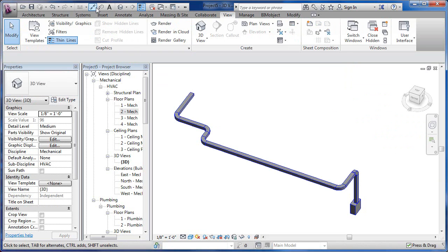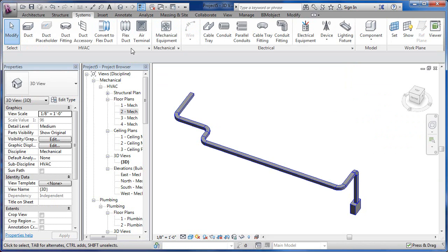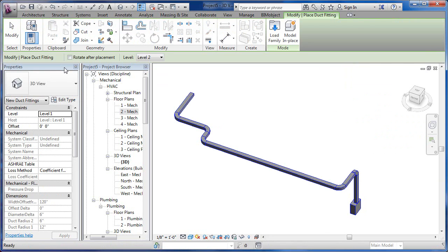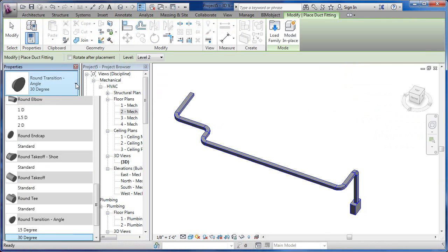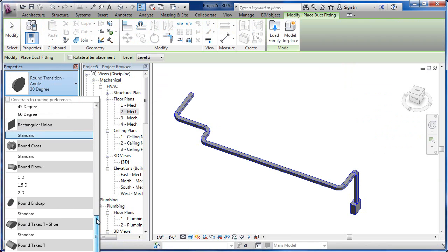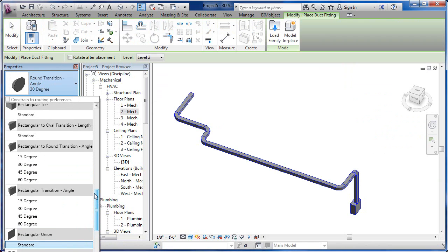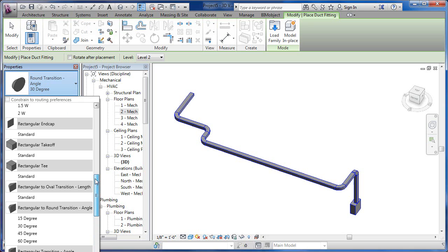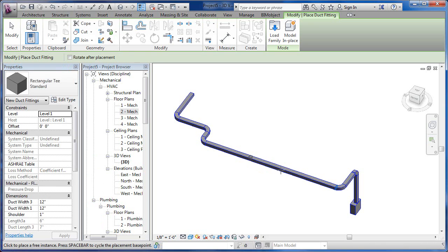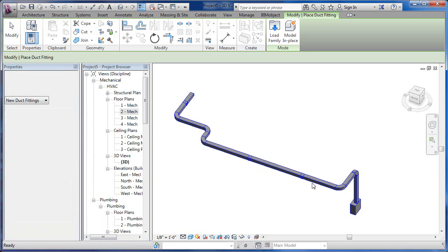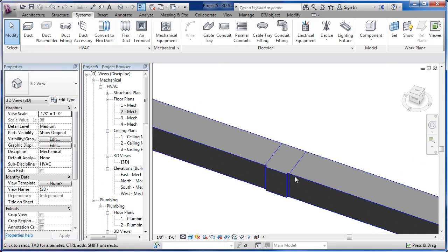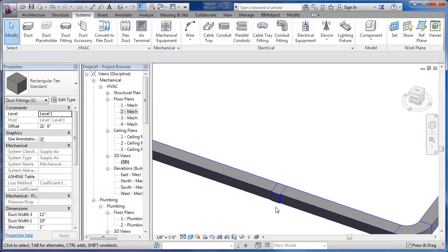Pick out. Okay, from there I could go into here and add in some duct fittings. Pick on here and say, okay, duct fittings. Scroll down and grab rectangular T or something. Rectangular T right here. So I could go in now and proceed to adding in some different fittings that I want to tap off of. Okay. Escape, escape. It's automatically going to splice itself inside of there, and it's going to have all its little connectors and stuff, which is nice.